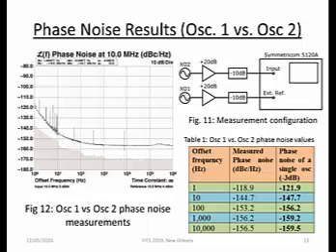For the measurement configuration that we used to measure reliably the phase noise of these crystal oscillators, we used 2 almost identical oscillators, one used as the external reference into the Symmetricom measurement system and one used as the input. This brings the noise floor of the instrument down and also helps avoid anti-correlation effects.